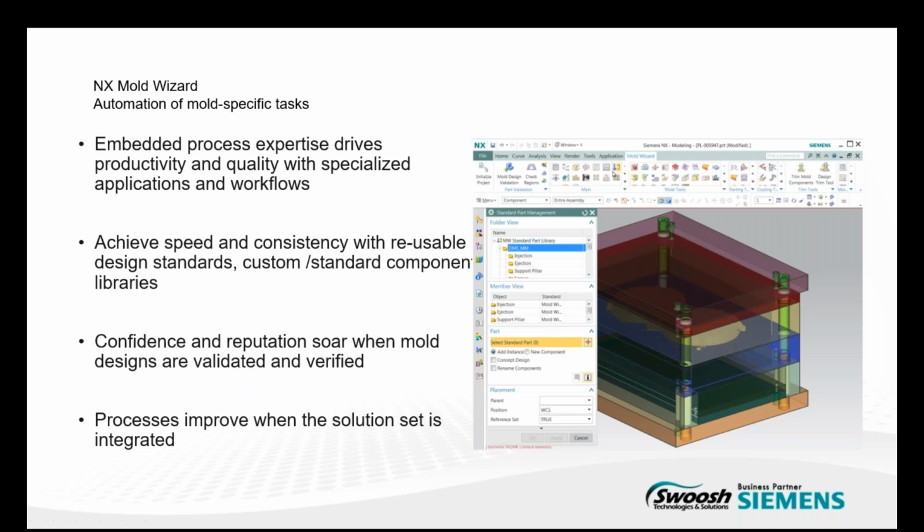Finally, Mold Wizard applies process wizard technology. Essentially, this automates the tools and the abilities within NX to design those molds, providing a structured workflow based on best practices, automation of mold-specific design tasks, and libraries of mold components. This provides you a step-by-step process that promotes the most efficient workflow while integrating complex elements of design technology into those sequences. Several of the capabilities, just to list a couple of them, are advanced parting tools driven by the power of NX, manufacturability checking for molded parts, automatic core and cavity inserts, or model swap for automatic updates to compare new versions.